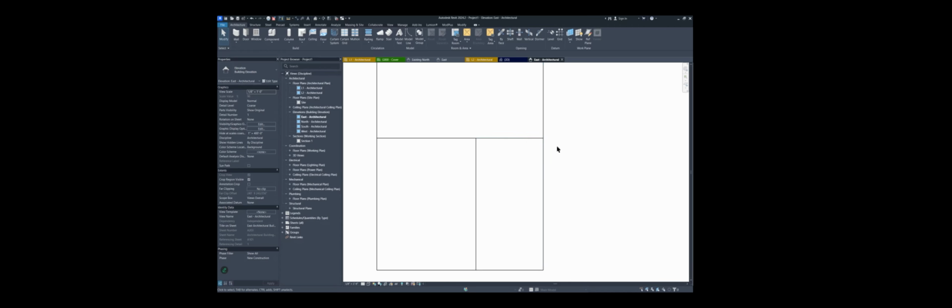There you go. Now if I look back on the elevation view, I'll make this a little shorter so it's more realistic. You will see a line here, but the line you're seeing is there because the building actually makes a corner like this. So this line is justified with it being here. But this line that separates these two surfaces shouldn't be there because they're on the same plane.